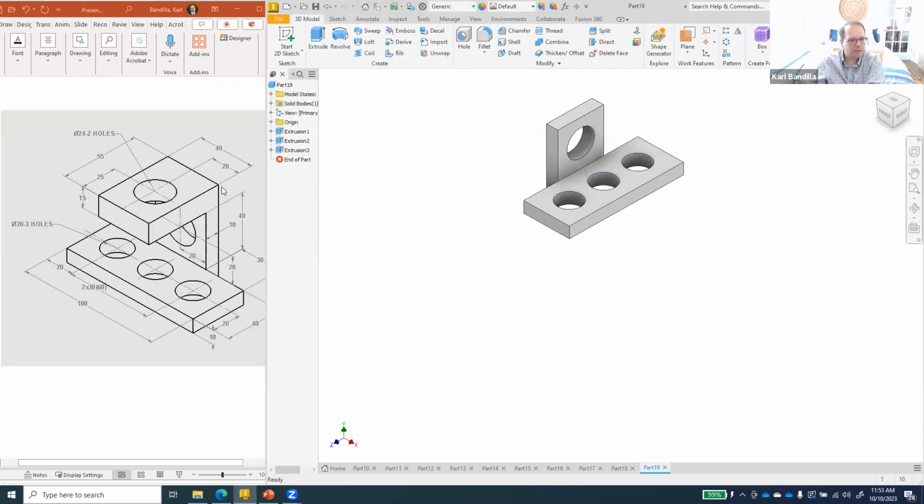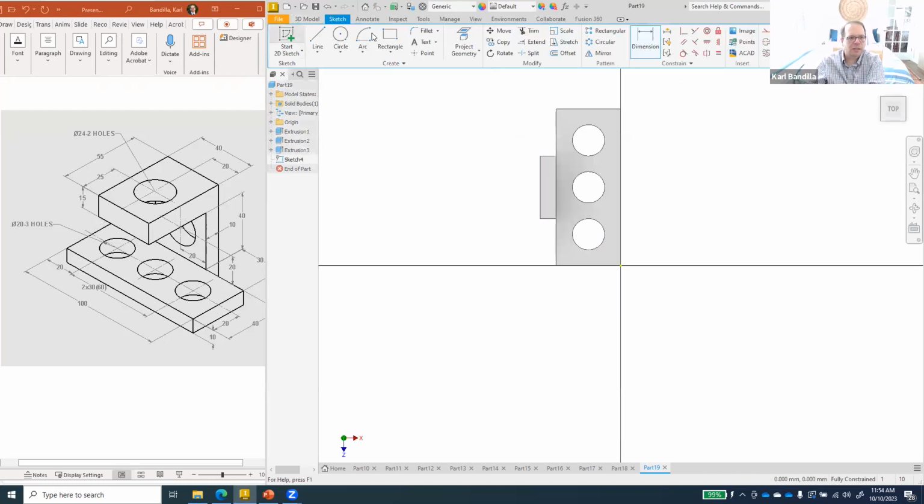Now all we need is this top part. So I would recommend that we just draw the bottom outline, put the circle in, and then extrude everything but the circle upward. So that means we need to draw onto the surface. And new sketch, rectangle. And then it is supposed to come out 55. The 40 we already have. There we go.